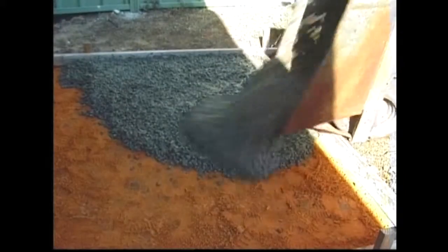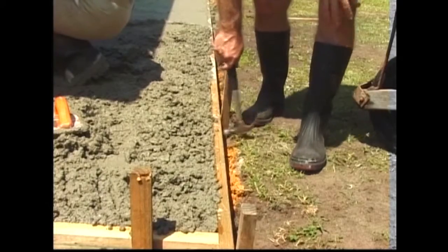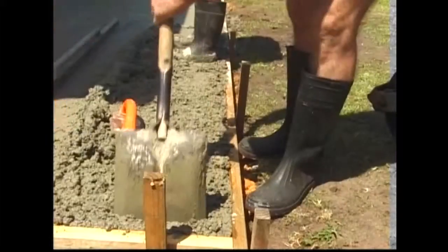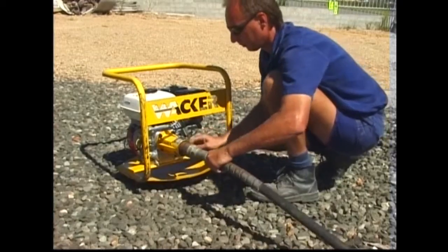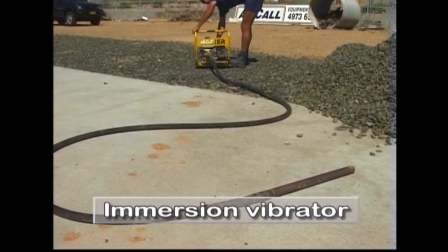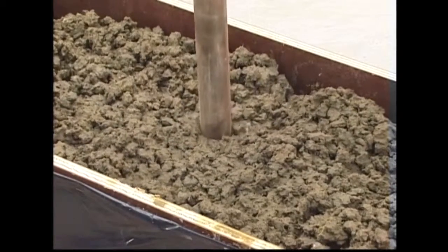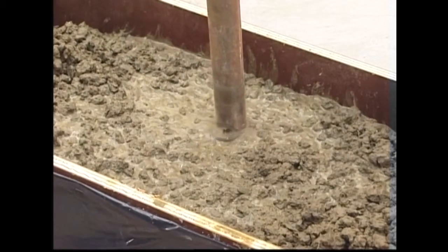When concrete is placed, air is trapped in the mix and must be removed. On small concreting jobs, this can be done by tapping the formwork or spading. On larger jobs, an immersion vibrator is used to compact the mix. The vibrating poker head is placed in the concrete and its action removes the trapped air cavities. The end result is a dense, durable concrete.